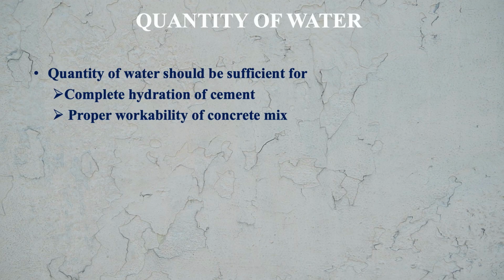Now let us see what is the quantity of water required in the concrete. Quantity of water should be sufficient for number 1, complete hydration of cement, number 2, proper workability of concrete mix. Because water is mainly required for these two purposes. One is hydration of cement, second is workability of concrete mix. So sufficient quantity of water should be there so that both these actions are fulfilled properly.